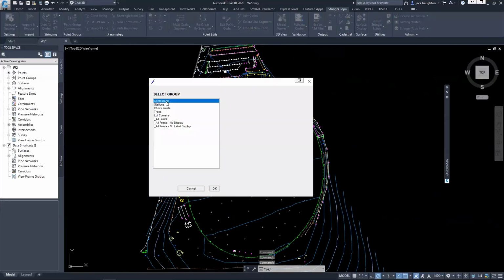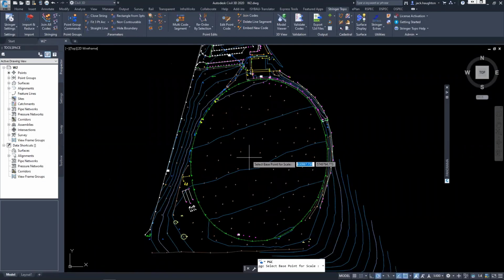But if we go back to this, the more impressive one is our scale function. Now, when you've been out in the field, you've done your GPS survey, you don't want to be scaling everything by the 3D plane. All the points you picked up, they're perfectly fine for height. You just want to change them in terms of your XY axis, not your Z. So what we allow you to do is scale everything, but only by the 2D axis. So your X and Y, we don't touch the Z axis. So if we run this, exactly the same as normal, but we've got our own little custom one. We can run this as per normal. You select your base, enter your scale amount of 0.999997, say. It's now scaled everything by that amount except for the Z axis, which remains untouched. So all of your points won't be touched with the Z.